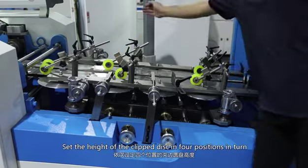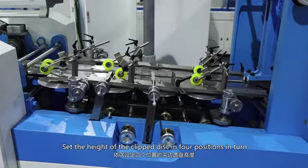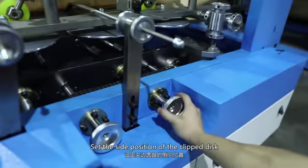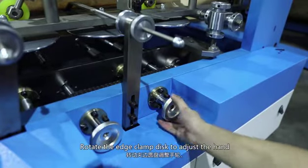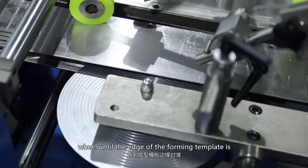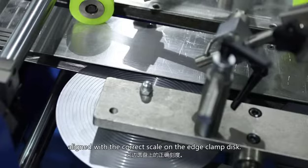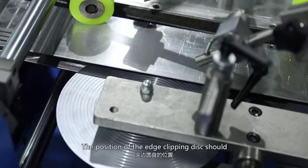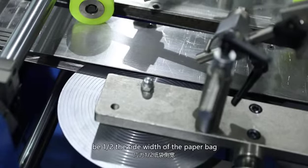Set the height of the clip disc in 4 positions in turn. Set the side position of the clip disc. Rotate the edge clamp disc adjustment hand wheel until the edge of the forming template is aligned with the correct scale on the edge clamp disc. The position of the edge clip disc should be half the side width of the paper bag.